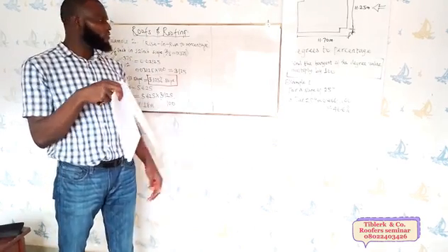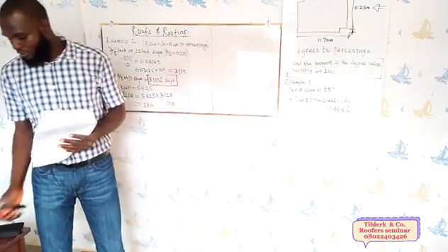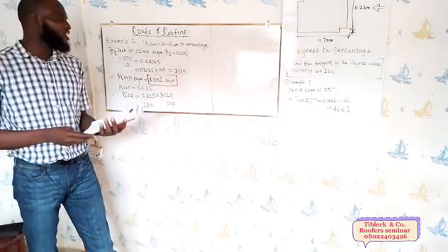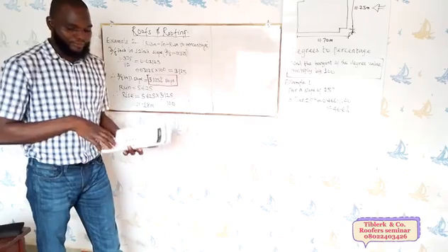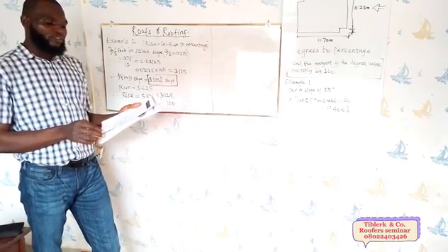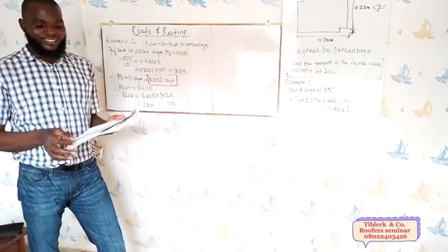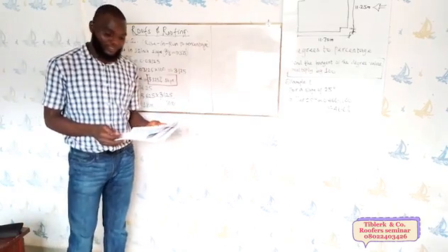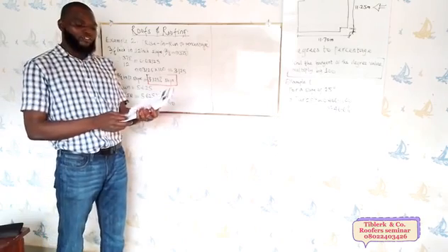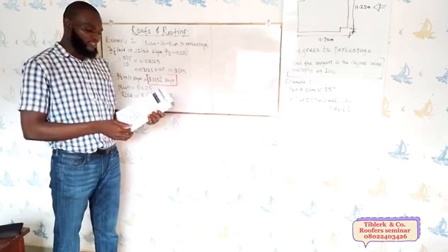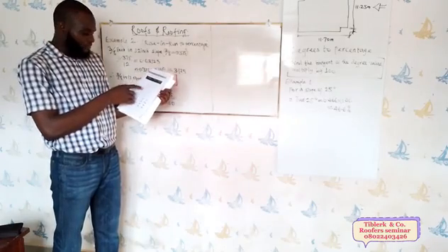Now, we have some values, a conversion table, in the material. A conversion table that has all these things we have been stressing ourselves over. They are there. Right from 0.5 in 12 rise, the equivalent degrees is 1.193 degrees, while the corresponding percentage figure is 2.08. Likewise 0.5 to 12 and the likes.